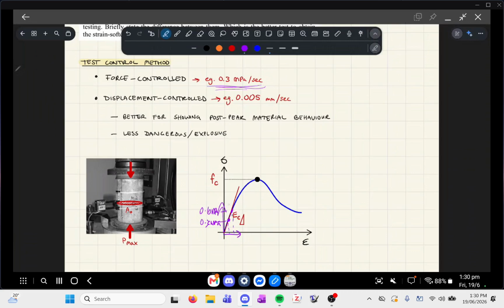So the problem with treating the force as the independent variable is that it can't be undone. Do you know what I'm saying? You can only increase the force, and so it doesn't know when to stop applying an increase of pressure. And so it doesn't effectively capture the material curve past this point, which is where it reaches its peak stress that it can handle, right?